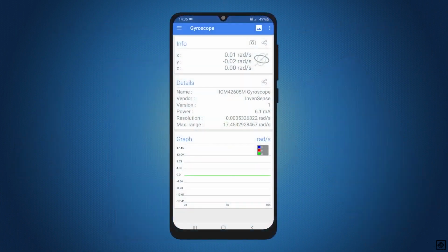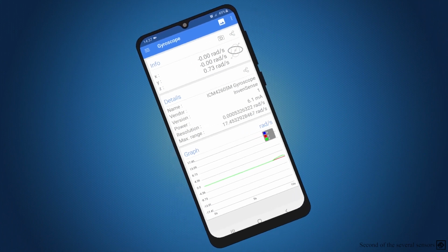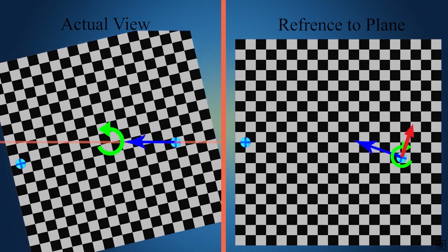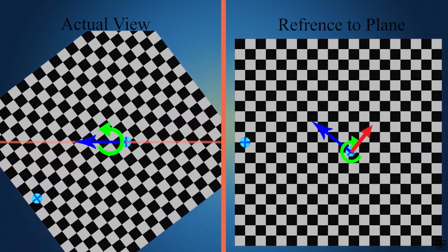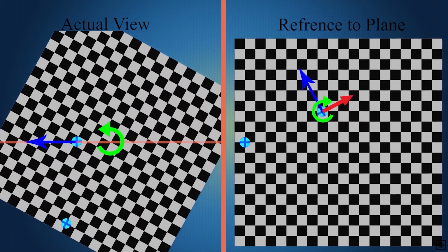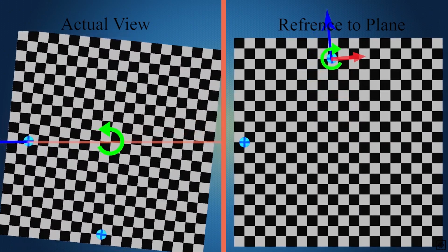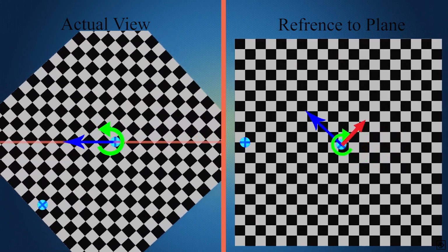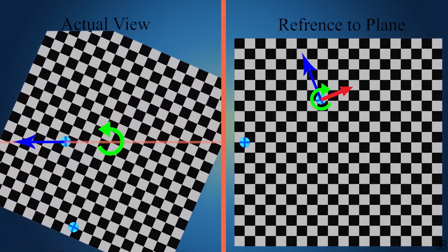Hence we introduce you to another sensor called the gyro sensor or gyroscope. A gyroscope is used to measure the angular rate using the Coriolis effect. It states that when a mass is moving in a particular direction, then a perpendicular angular force applied to a moving mass creates a force perpendicular to both. If we detect the acceleration of this force, we can calculate the value of rotation.